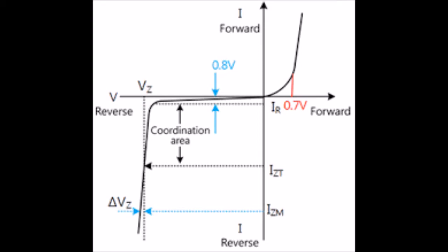As the reverse voltage increases to the predetermined breakdown voltage, a current starts flowing through the diode. The current increases to a maximum, which is determined by the series resistor, after which it stabilizes and remains constant over a wide range of applied voltage.